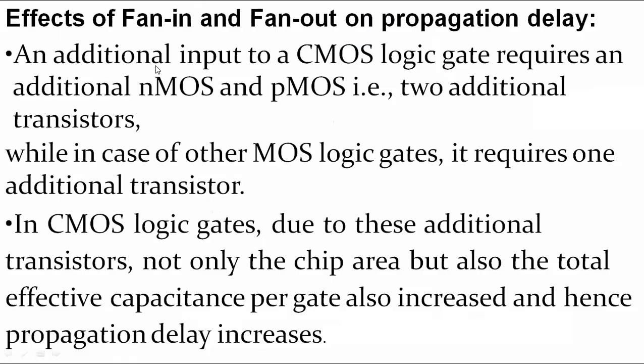Additional inputs to the CMOS logic gate require an additional NMOS and PMOS, that is 2 additional transistors.